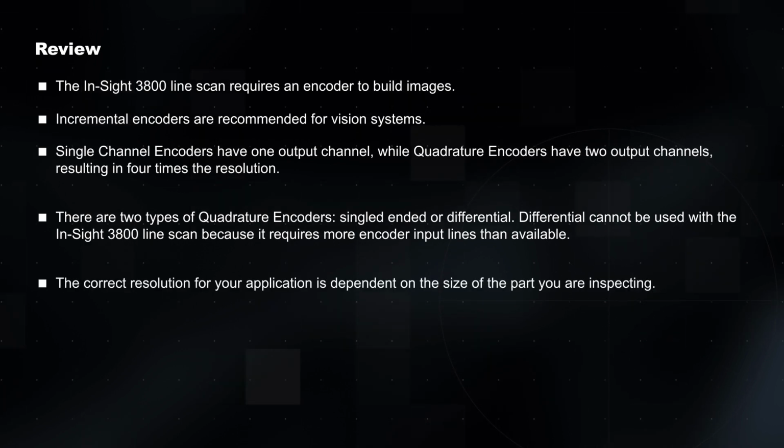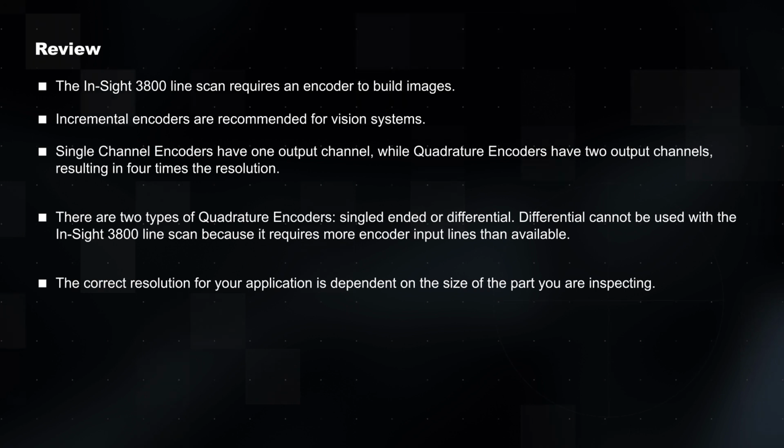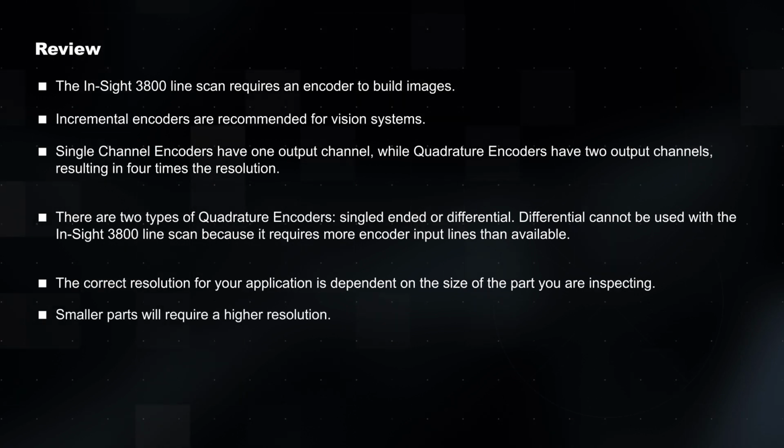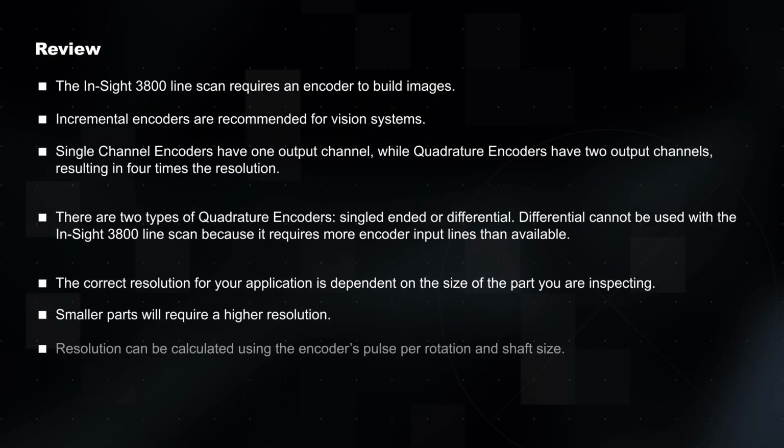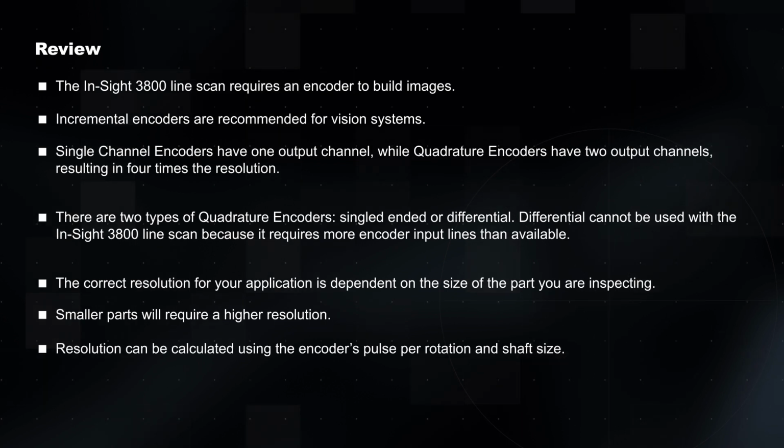The correct resolution for your application is dependent on the size of the part you are inspecting. Smaller parts will require a higher resolution. Resolution can be calculated using the encoder's pulses per rotation and shaft size.